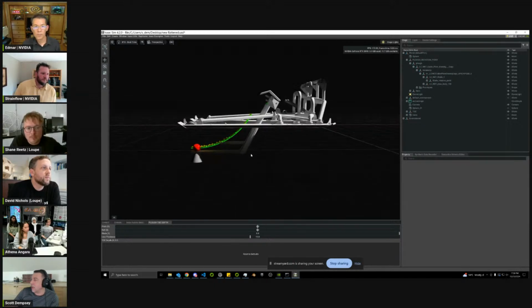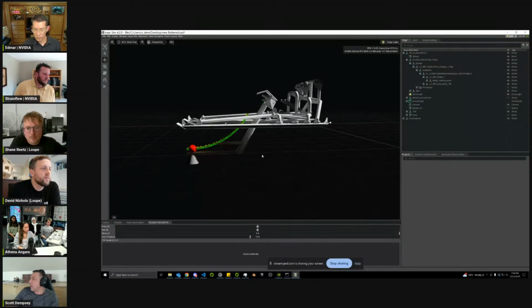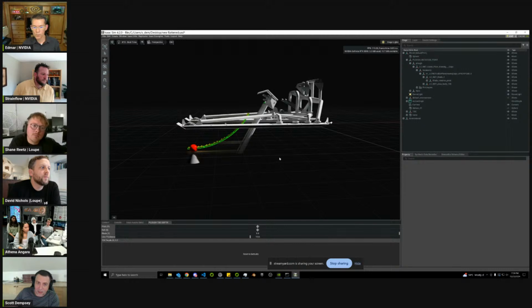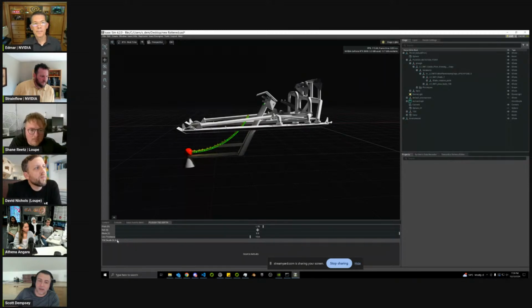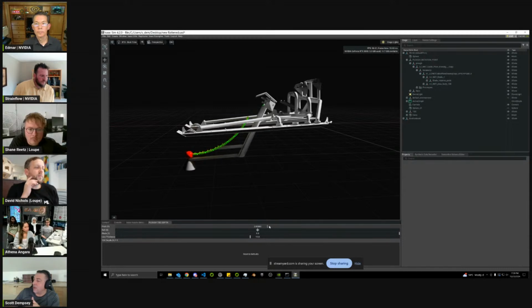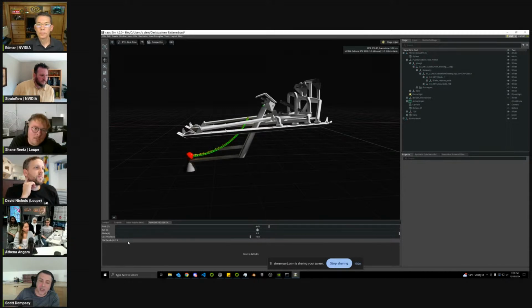So one of the things I wanted to look at was how to visualize that. I imported the CAD model, then flattened it to OpenUSD, which is a really simple, really easy process, and then built an extension. In this little extension, we can induce pitch, so I can find out what the lowest point is. Say my burial depth is now 6.4 feet, but as I increase the pitch of the robot, I can see at what burial depth it's now at a specification.